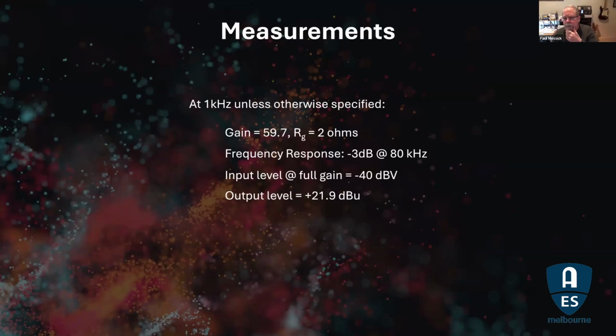Back up here. So you'll see me switching between dBV and dBu quite a bit. I use dBV because it's more intuitive, because most of these are voltages, and dBV is indeed, as Rod says, dB relative to 1 volt.